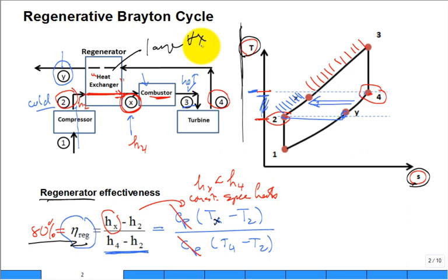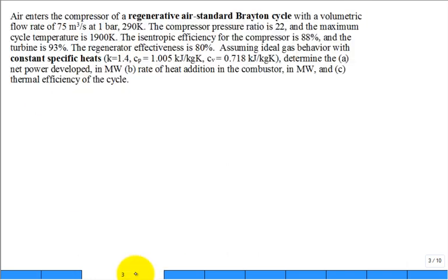Okay? But the principle behind that is if I need to move this much heat, the rate it's transferring, it's some convection coefficient, often that's low for gases, and some area, so you want some large area, and then some delta T. Well, we'd like this delta T to be restrained. It's maximum delta T. Usually this is a log mean temperature difference, something like that in the heat exchanger. And if you want a large Q for the fixed h and delta T, it's pretty basic. Make area large. Big area. Okay. So we can solve a problem.